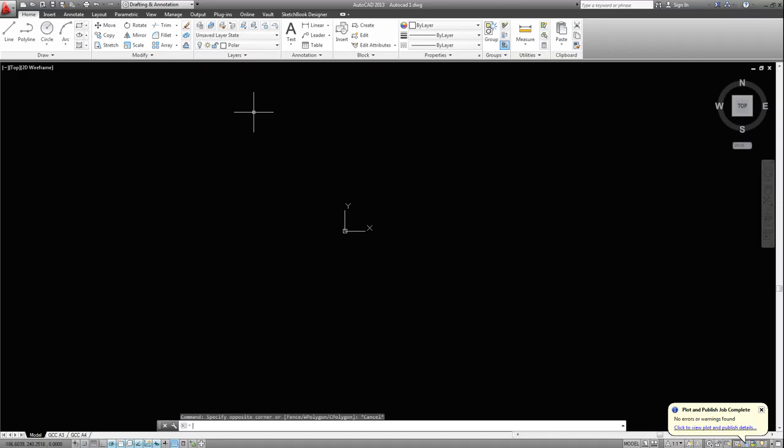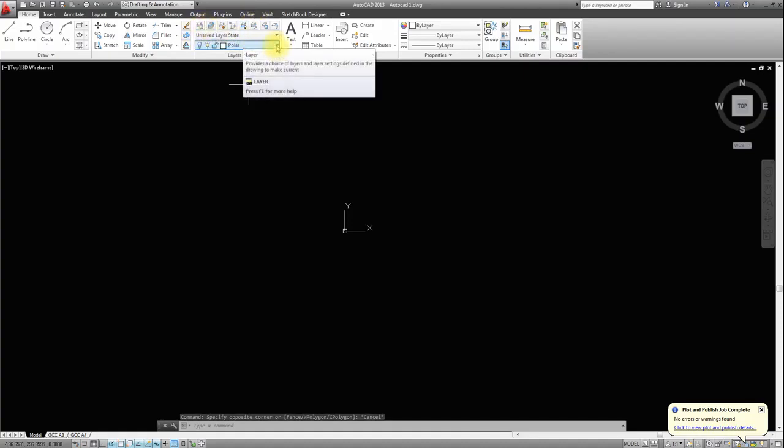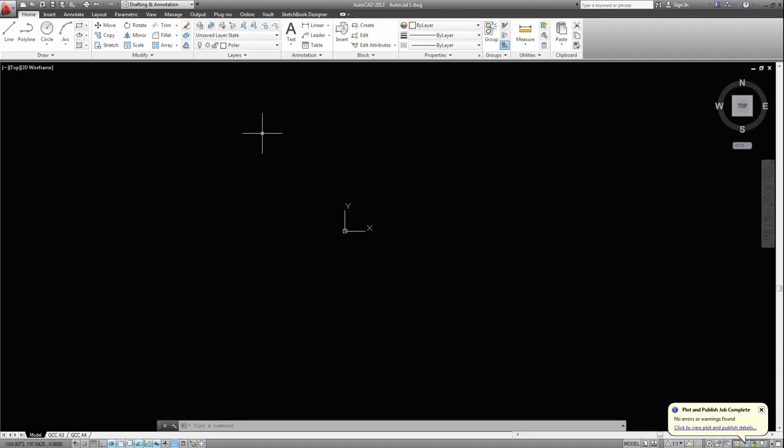If you wanted to see the basement, you had to fold those layers away so you could see the drawings in the basement. So what AutoCAD's done is created a system of layers, so it basically gives you the same thing. You can build and draw in different levels, and because of the way that it works, you can actually turn a level off if you want to be able to see what's below it.